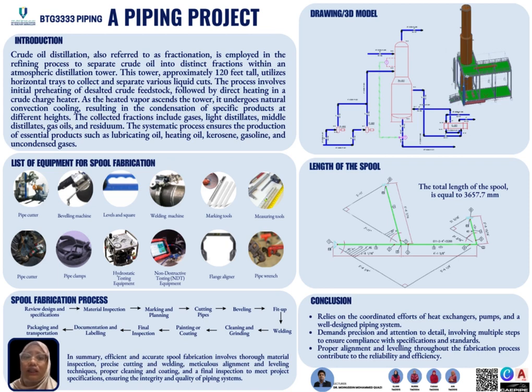And sixth, assembling pipes, fittings, and flanges according to the drawings is our fit-up step. Tack welds may be used to hold everything in place. Now the magic happens. We weld the joints, using different techniques. Make sure to follow the procedure.